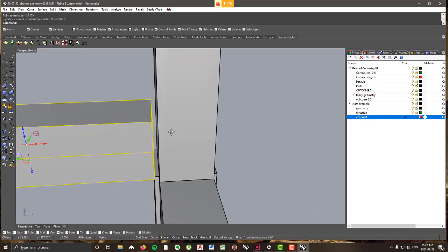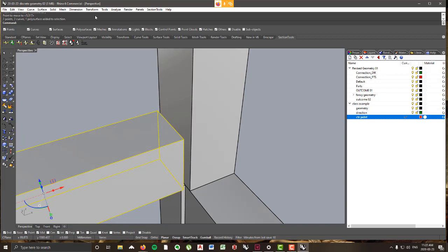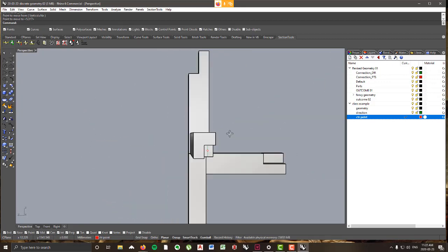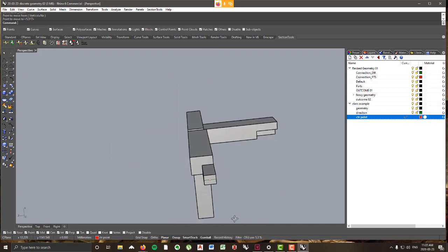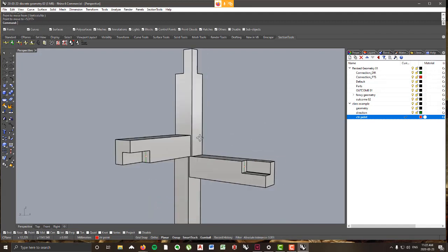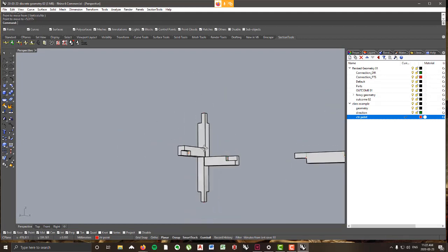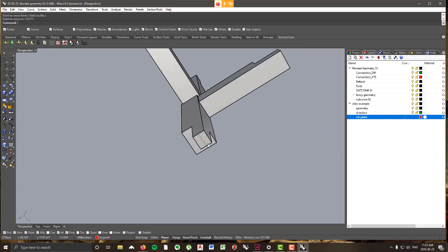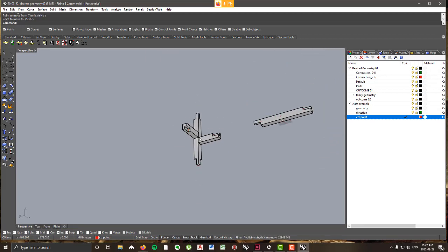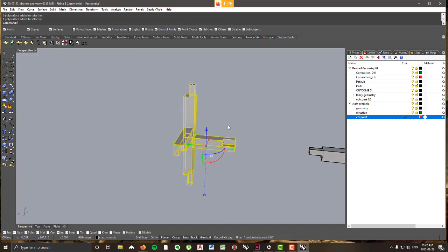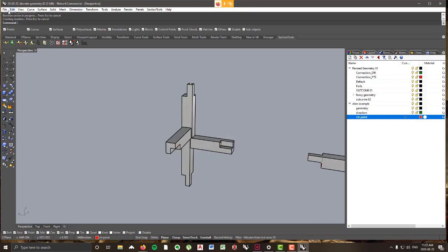So essentially what I'm doing here is I'm just trying to make this piece look somewhat nice. If you're actually using this method for your assignment 3, you're going to want to take care to design these pieces a little bit better so they fit together in a meaningful way. For right now, I'm going to say this is good enough. Essentially, I've just created a connection piece and I've maintained the connection center points and directions. What I'll do with this geometry now is I'll just select all these brep components. I'll hit Boolean Union. And from here, I'll save in the Dropbox.